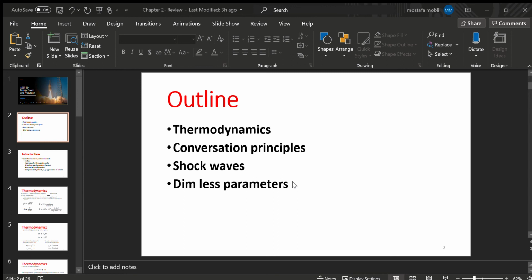Let's move to the isentropic processes. What is an isentropic process? Reversible and adiabatic, right? So for an isentropic process, we can rewrite the relationship between the temperature, pressure, and also the density for a calorically perfect gas. What was a calorically perfect gas? When Cp and Cv are not a function of temperature, right? Or constant, as far as temperature is constant.